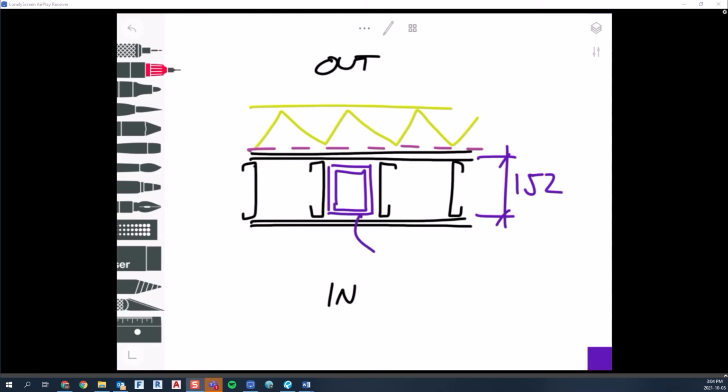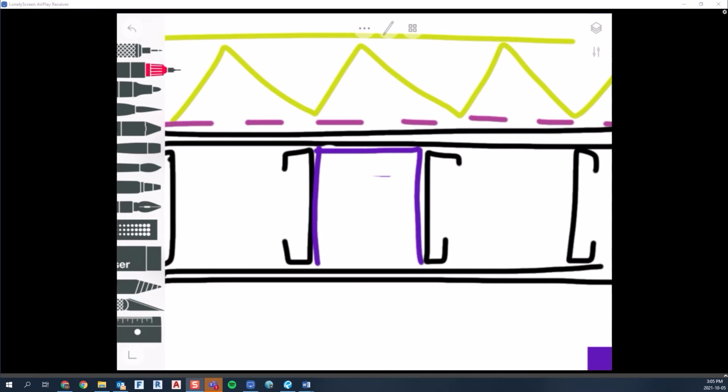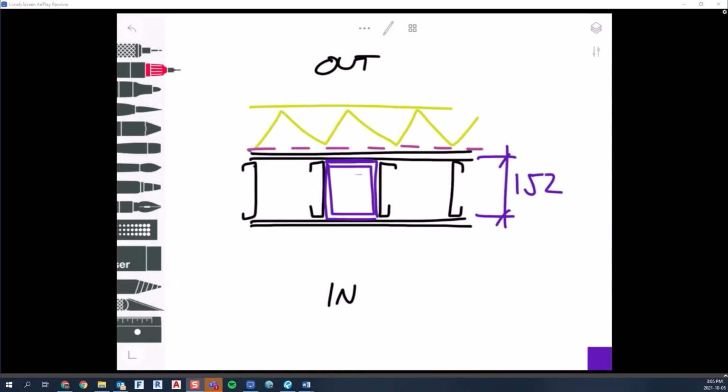So that would just mean you got to make sure that that column is not bigger than 152 by 152. Or I guess it could be a rectangle, but the square HSSs are pretty common, basically. So I did a lot of buildings like this. What we did for years, actually, if it was a smaller retail building, let's say, with not real high ceilings, we would actually do the 6-inch column with the 6-inch stud. And it just barely fit.